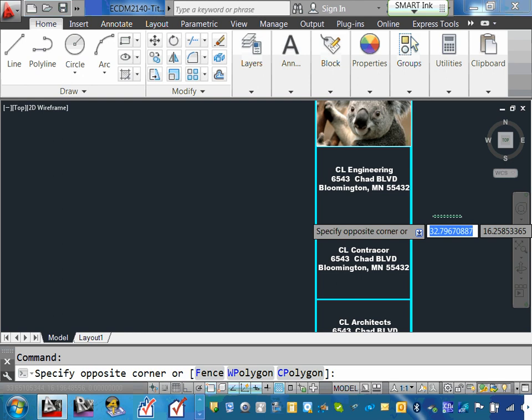What I would do, is this the same distance? When you copy them, did you copy them with the reference point? No. Yeah, see, when you copy, if they're the same reference point, they just sit right there. Otherwise, well, let me just try one. Okay, let me just copy. Kept the same name on it. Yeah, gotcha. Copy with the reference point. Here's my reference point. Zoom a little bit on. Okay. Right there.